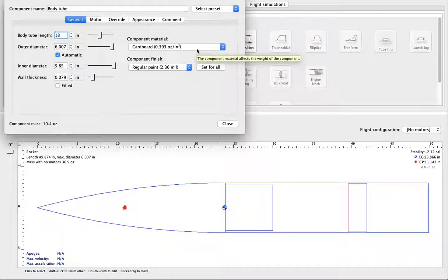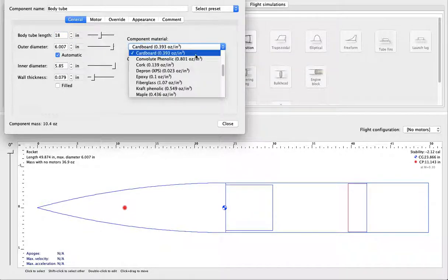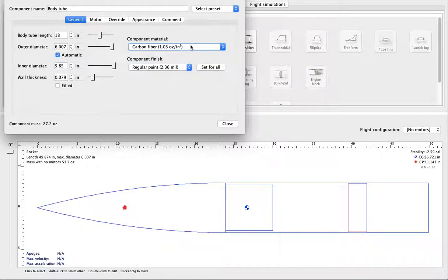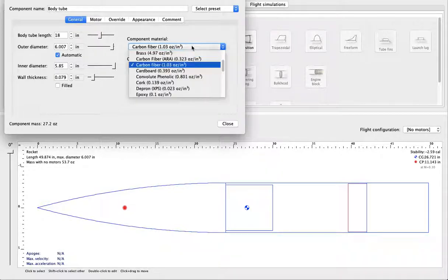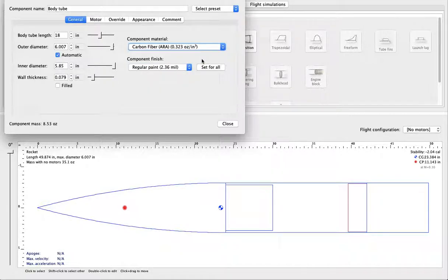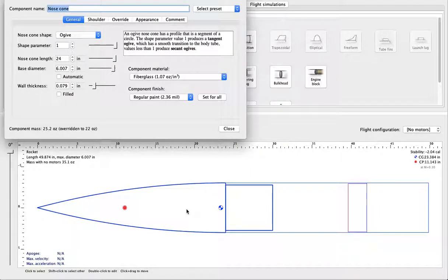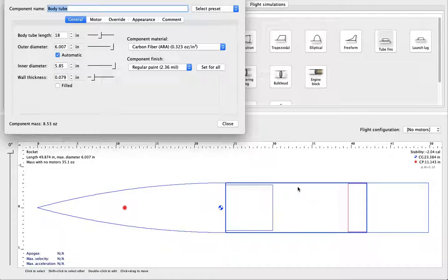When I say roll, we put carbon fiber on an aluminum mandrel and pump liquid nitrogen through the mandrel to shrink it so we can slide our carbon fiber off. So I said carbon fiber. Let's look for it. All right, here we go. Now here's where things get a little sticky. Our carbon fiber, we calculated the density, and for the tubes we roll, they're much lighter than this kind. It's a much more accurate simulation if you weigh your own things, and I know that I said these are certain weights and measurements, but you really want to wait till you get the actual component, like actually get the nose cone to weigh it and make sure OpenRocket is really simulating to the best of its ability.